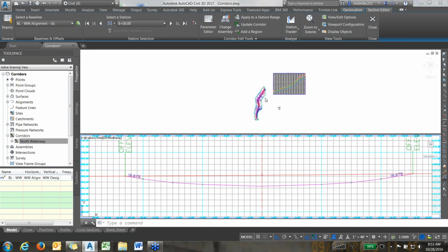The thing I wanted to show you, though, is that I only showed you how to do one grass waterway size. I'm going to show you now how to do more than one grass waterway size in the same waterway. So say the grade changes significantly to where you have to go to a 50-foot wide grass waterway 2 foot deep, or if it's flat up top and you only need to go, say the standard alternative design is 32-foot wide 1 foot deep, okay? That's the one I'll show here today.